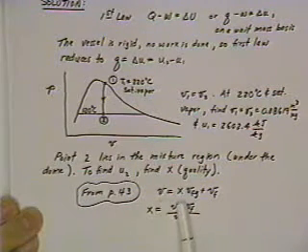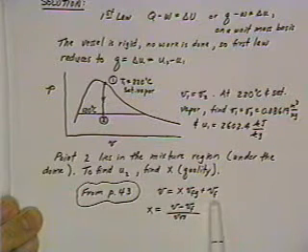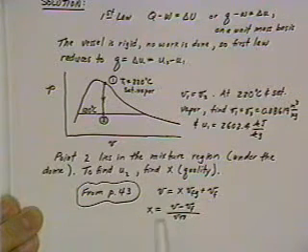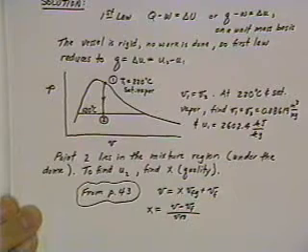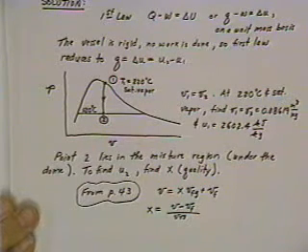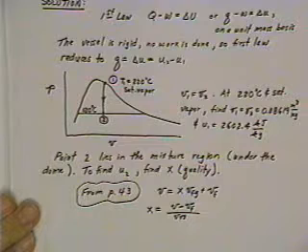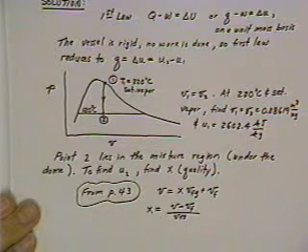So V is equal to X VFG plus VF. The quality is the key term that you always have to find whenever you're in the mixture region in order to find the properties that exist at that particular point.